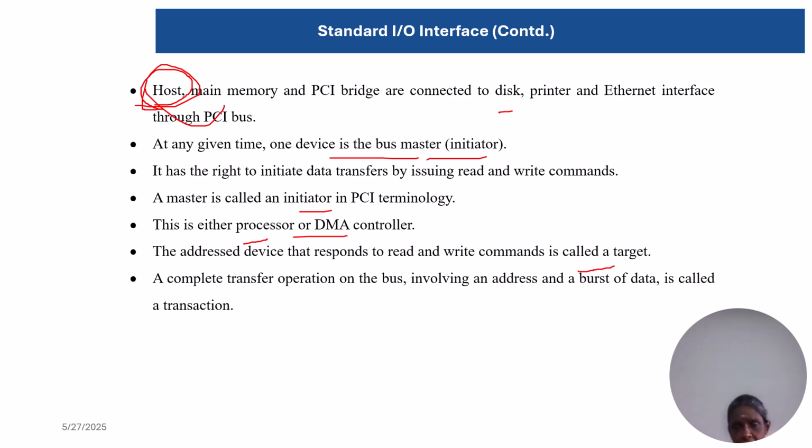When those addresses are called by the host, the respective devices recognize them and respond to the read or write operation or other commands. So those addressed devices are called targets. A complete transfer operation on the bus, involving an address and a burst of data, is called a transaction.